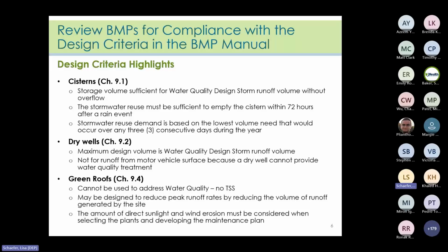Green roofs do not address water quality as they are usually above vehicular surfaces in elevation. They create opportunities for evapotranspiration and can be used in volume reduction calculations. That section starts on page 13 of the chapter for green roofs.